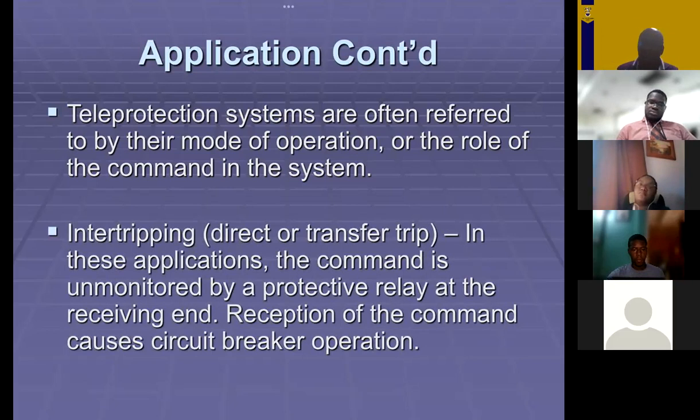So the system, we will call it inter-tripping or direct transfer trip, because the command, which is unmonitored, allows or causes circuit breaker operation. So the mode of operation is unsupervised receipt of a trip signal via your medium.